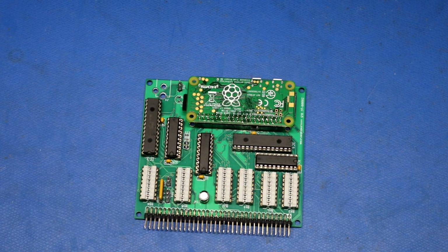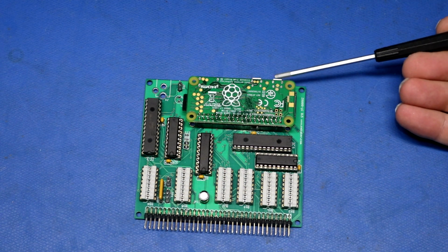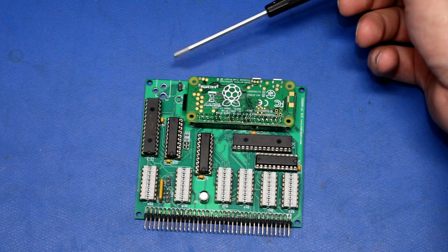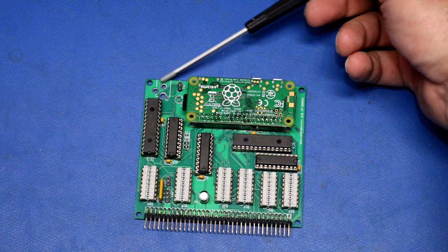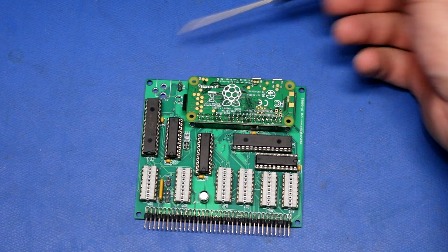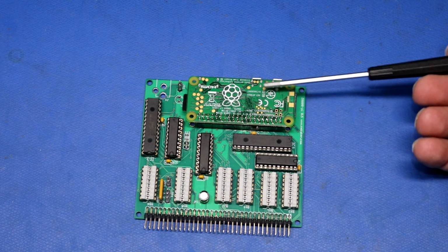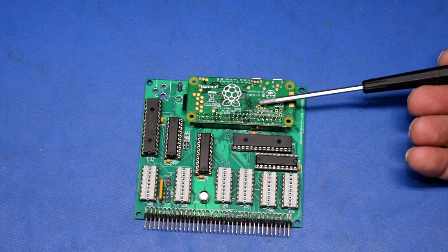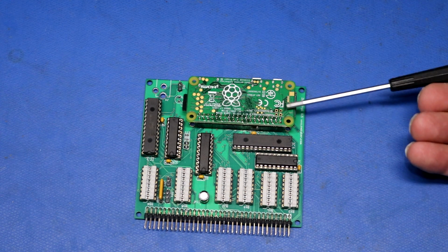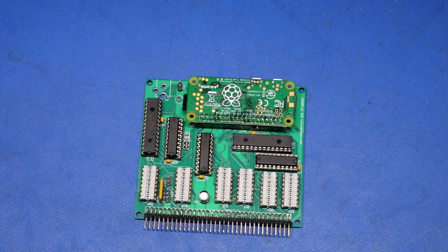Here is the bus supervisor board. So we have the Raspberry Pi Zero W mounted upside down. It's got its little SD card there. You can power it from the power jack there, as well as power it from a barrel jack here, which I haven't even bothered to populate. And you can jumper it so you can power it from the rest of the computer. I like to give it a separate supply, that way you can shut off the retro computer without having to shut off the Raspberry Pi.